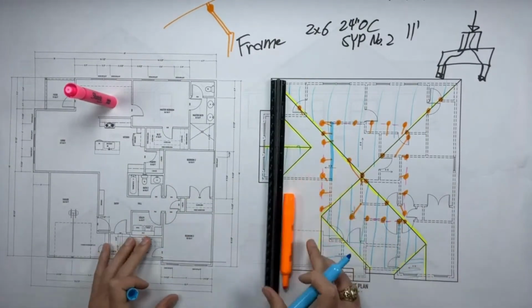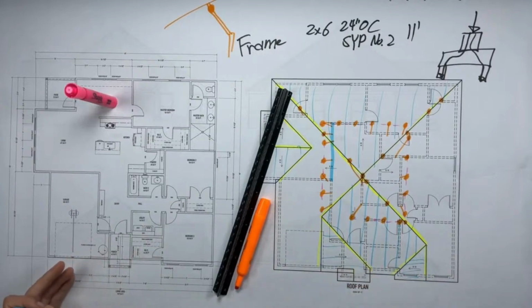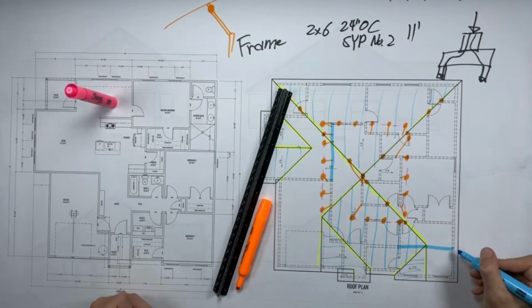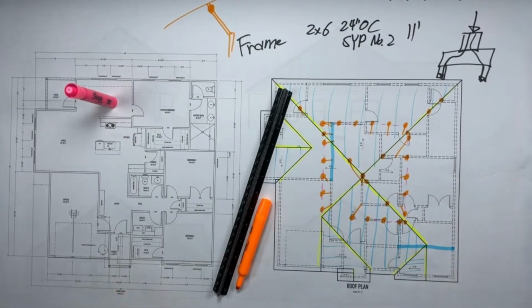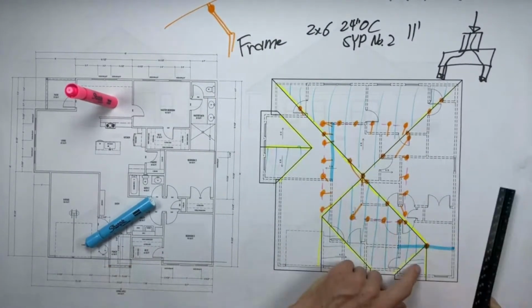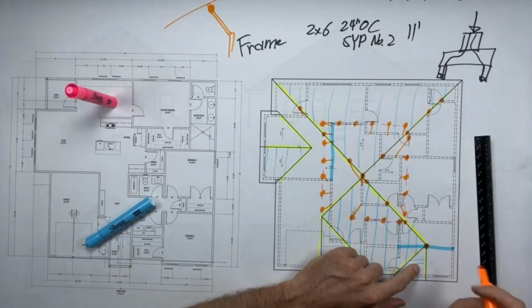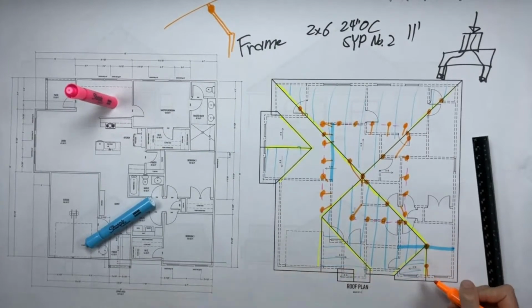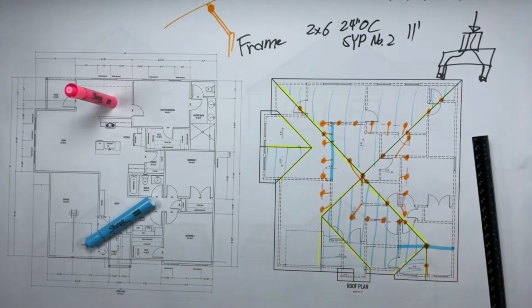There's really no difference. It's going to come down to which way would I rather run my ceiling joists, and they're probably going to go right to left. And I'd rather put the beam in where I'm in line with the ceiling joists, just so I can not fight them and not use a bunch of metal hardware and stuff. So that's right in the middle underneath that. So that supports this. This guy, I should probably put one brace in here. So I'll brace it here, but I'm high enough that I could probably go right back to this wall. So that one's braced off there.